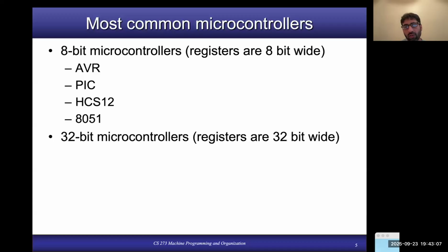For example, in AVR, you have an instruction, let's say, branch equal. So maybe in 8051, they have an instruction which does exactly the same thing, but the name of the instruction is different. For example, it says branch if zero instead of branch if equal. Okay. So that's why if you write a program for one microcontroller, you cannot simply port it to a different microcontroller.